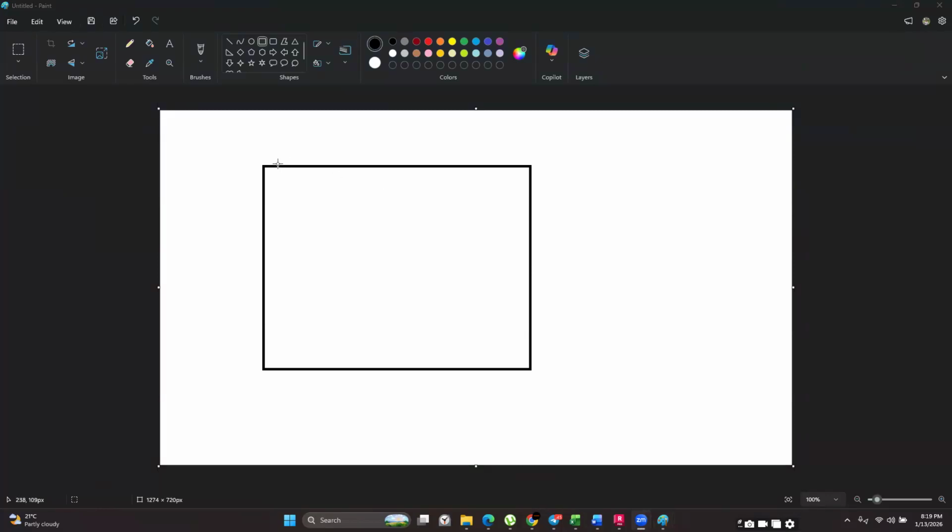The restrained slab is majorly the degree of, how do I say this? The degree or the principle between restrained slabs and unrestrained slabs is, if you're going to have any member as a slab and it is resting on beams, if it is not restrained, it means that you are going to be allowing these edges here to be deflected upwards. It means that at these edges here, you're going to be allowing them to be deflected outwards or upwards.